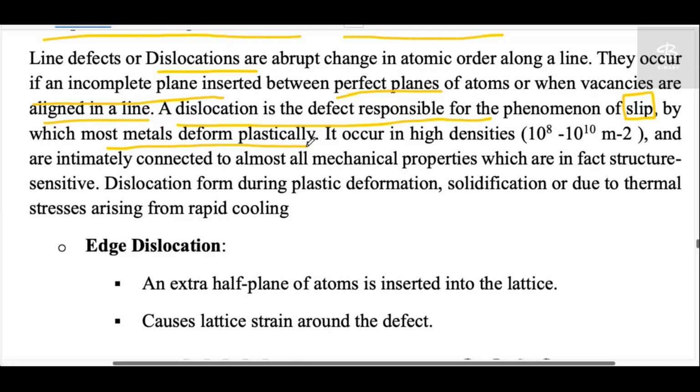The deformations are of two kinds, elastic and plastic. When you apply the load, not a stress. Stress is an internal phenomenon. We cannot apply the stress, we can apply the force, we can apply the load only. Once you apply the load, the material property inside the material, which we cannot see, resists that force. And the resistive force per unit area is known as stress. In general, we mostly think that whatever force we have applied is stress. No, that's not the stress.